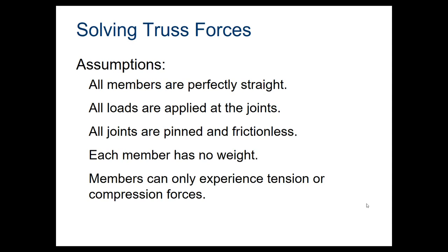The one that's also a big one here is that we're assuming it has no weight. Each of those beams is weightless, and that's a big assumption, and that's one that's definitely not realistic. But the assumption is that the load that we would be putting onto the bridge is going to be much larger than the bridge weight itself. And so we're going to ignore the weight of the bridge. That's obviously not a good deal, but just keep it simple. We're going to go ahead and do that.